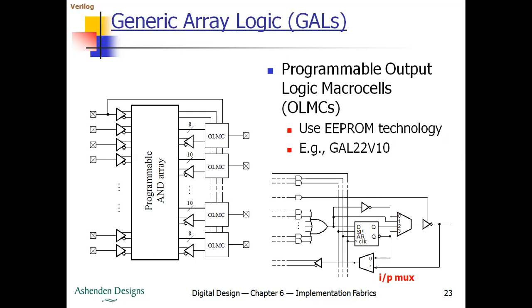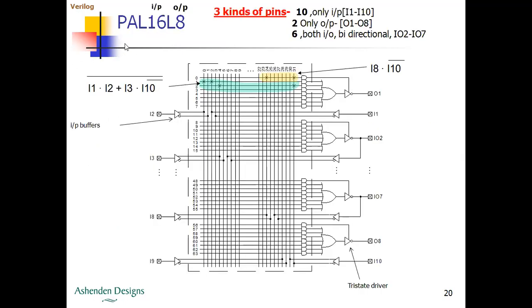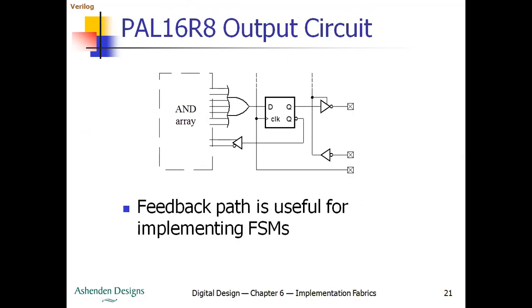From an examination point of view, they may ask you to design the PAL16L8, or explain the architecture of the PAL16L8. Why the name PAL16L8, information regarding the number of only input lines, only output lines, and how many pins can act as bidirectional pins, the manner of connection between the vertical and horizontal lines, and the use of the fuse, along with the tri-state drivers at the output end and the input buffers. All these things can be explained here.